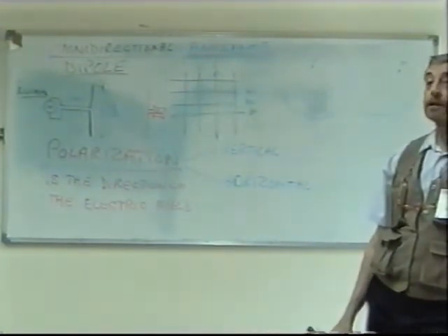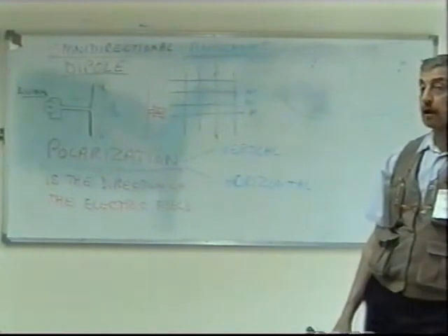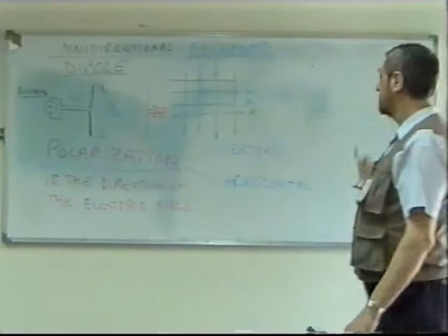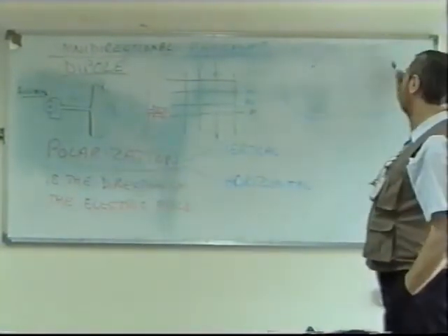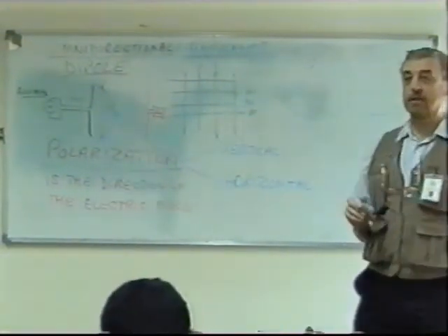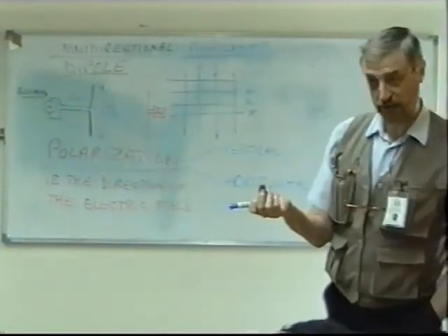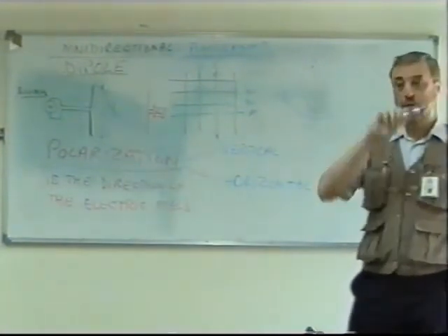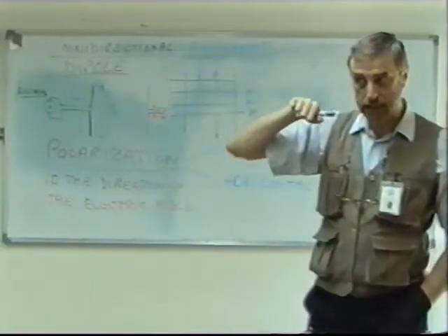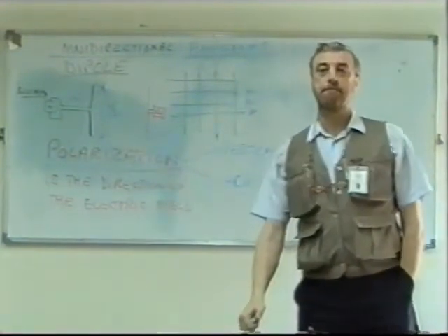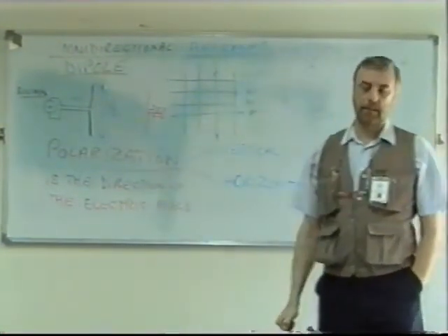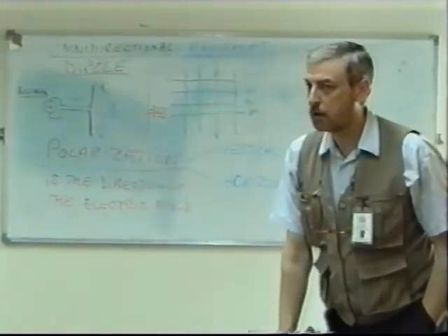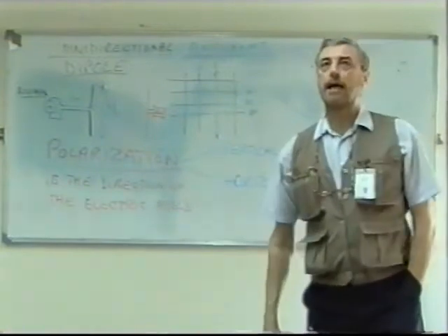But you just mentioned that after the signal hits the ionosphere, that's HF. This is not HF. This is direct line of sight communication. We're talking about broadcast TV, which uses VHF or UHF. Now, with VHF and UHF, of course, we're not bothered about reflections. It has to be more or less line of sight. HF is the only frequency. Basically, yeah. We won't use dipole antenna for HF.